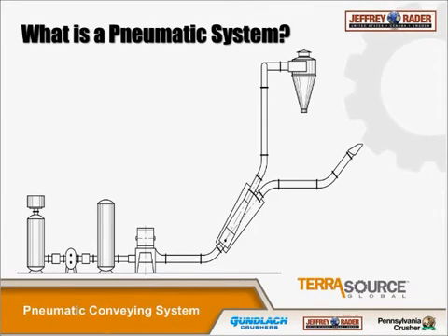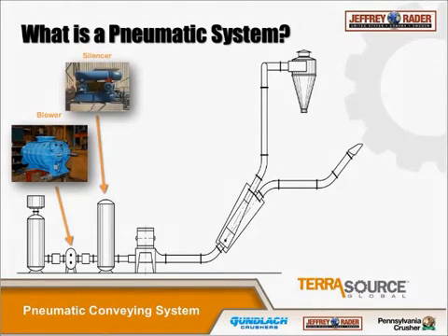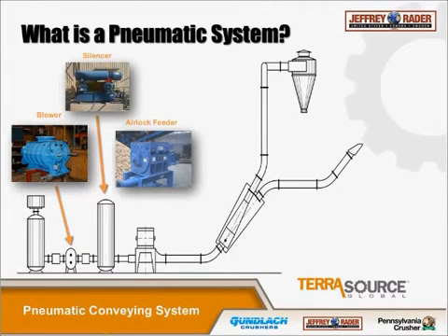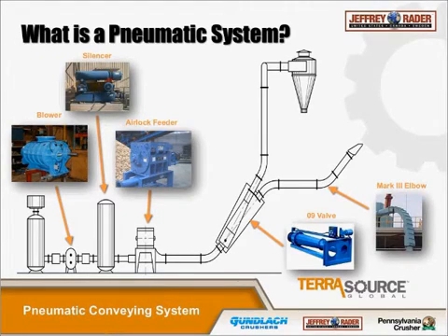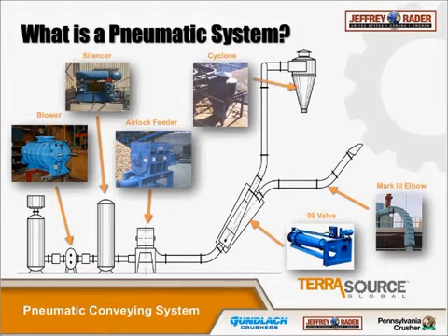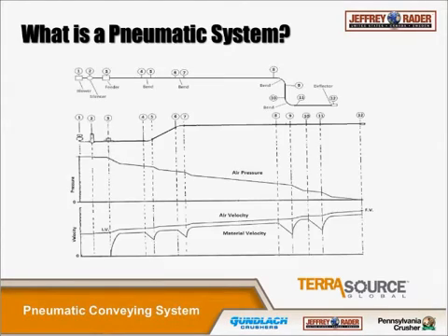So what is a pneumatic system? A pneumatic system is simply a method of transporting material on a moving airstream. You have a blower that generates the air. Should be inlet and discharge silencers to reduce noise level and tame pulses. Material is introduced to the piping with the ESW feeder. Might include a diverter valve for multiple discharge points. Should have some elbows in the system. Might have a cyclone that's useful for discharge into a bin. And you might also have a deflector nozzle which blows into a pile. These are just some examples. We'll get into some of those other discharge devices later.